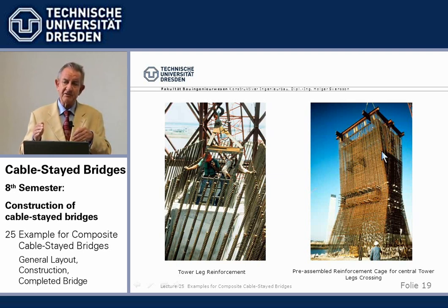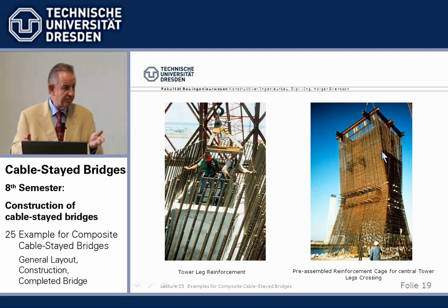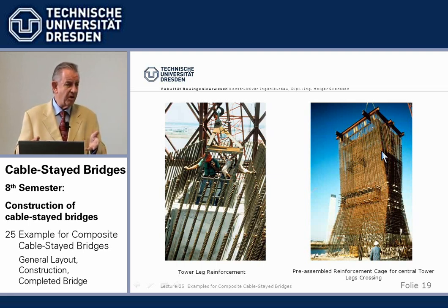special graded aggregate, not the usual 0 to 32 millimeters, but 0 to 16 millimeters, special design, plus super plasticizers, which makes the concrete really good flowing, and it worked. It was possible to cast this part in a good way, and when we took away the forms, no honeycombing, you know, the aggregate showing up, it looked very nice. So it was just possible.